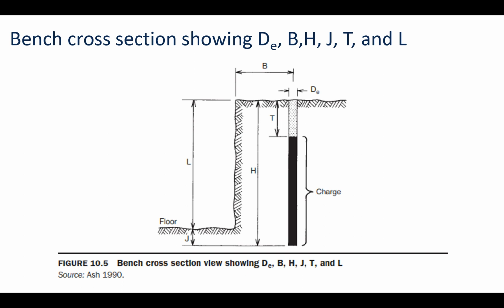In fact, in coal, what we usually do is we'll drill to the seam, and then also add 3 to 5 feet of stemming material to pull that charge up off the coal. That way you don't break the coal and lose it when you're loading out the rock.